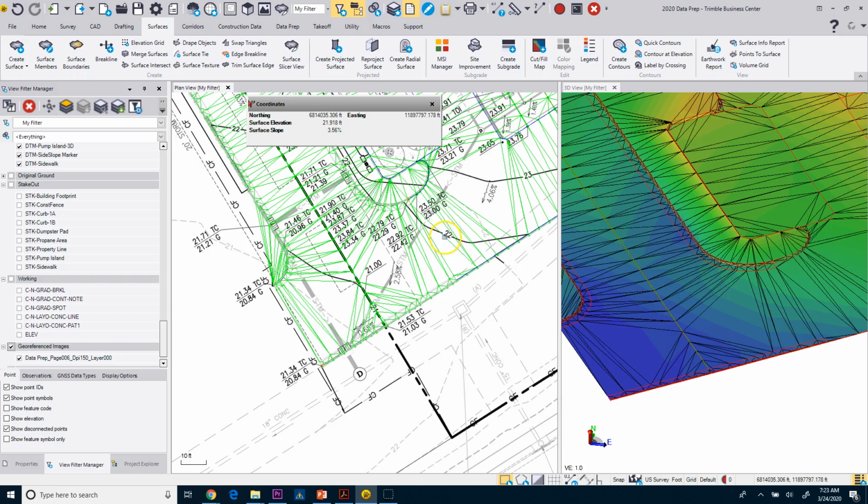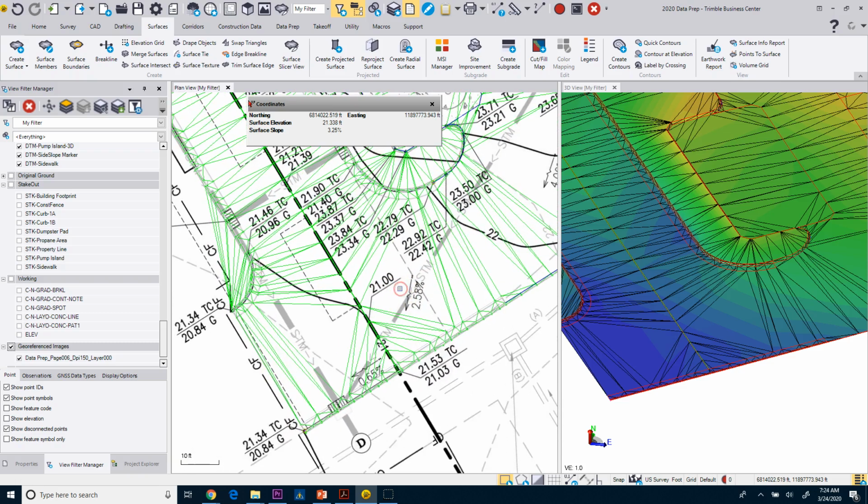Again, that's going to be up to you and what you want to do. I personally don't think it's necessary for the most part. I guess again, there's some different discussions that could be had, but down here is something I want to show you: how adding a break line changes the slope. So if you look here, I'm at like 3.25 and it's supposed to be 2.58, and you can see because it's triangulating like this, and maybe it really should triangulate from here to here.